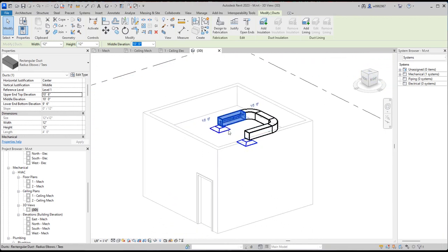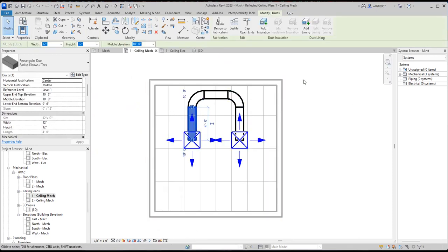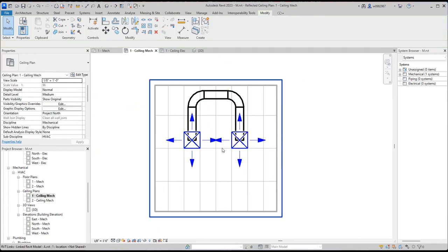You have a link file. You're putting your ductwork on the ceiling, and you are looking upwards here on the ceiling, so that's why this one is going there. You can also change this one to shaded. You can see that this is the ductwork. Below it is your air terminals and supply air terminal.